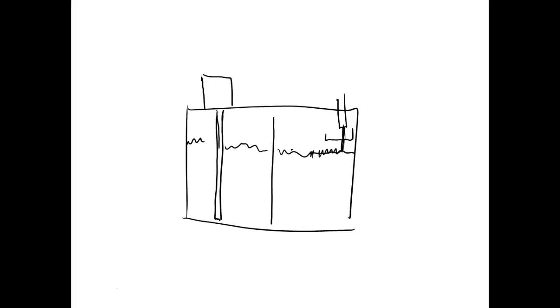So the bubbles will be riding on the top. They can't get across anyway because of the baffle. So with this baffle over here, as long as we don't create a suction tube over here when it's trying to suck, then we're not going to get bubbles in there anyway. If you ever looked at a brake cylinder on a car, you notice that the output is down at the bottom.